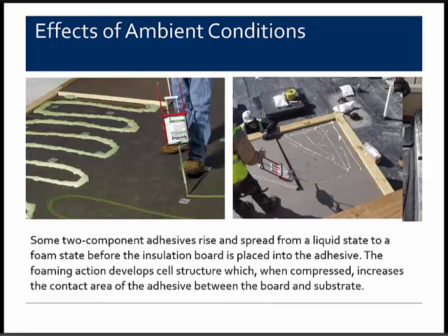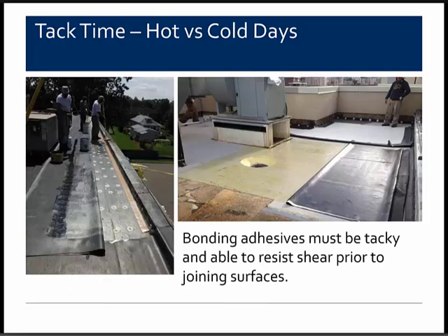The tack time for the various adhesives, whether it's a hot day or cold day, is going to vary depending on the ambient conditions. The bonding adhesives must be tacky prior to bonding the two substrates together. They should be able to resist the shear prior to joining the surfaces.